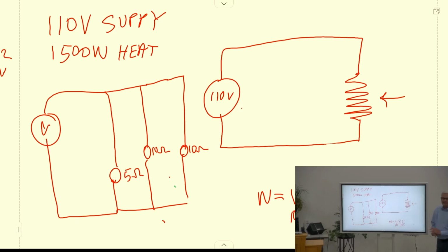And guess how I get my voltage up to 10,000? A transformer. I can't run 10,000 volts inside the generator because it's going to arc. It's going to be hard to make my generator put out 10,000 volts because of other physical constraints of the windings and the insulation and all that.